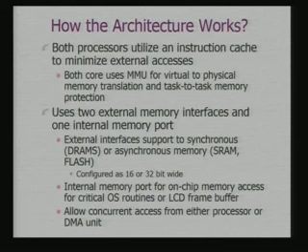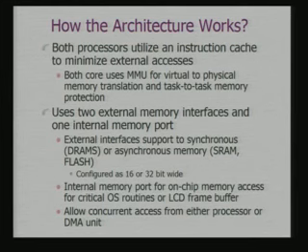Your critical OS routines are expected to be loaded on the chip itself, as well as the LCD frame buffer. In fact, if it is targeted for mobile applications, there would be a requirement of a display panel, and the data to be displayed on the panel is stored in a frame buffer, which is again a memory area where you have a mapping from each pixel on the display to a memory location in the frame buffer. That would be very frequently accessed, because there you actually have updates to be displayed to the user. So, that also forms part of your internal memory.